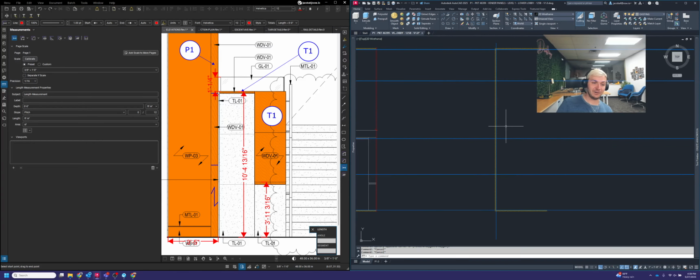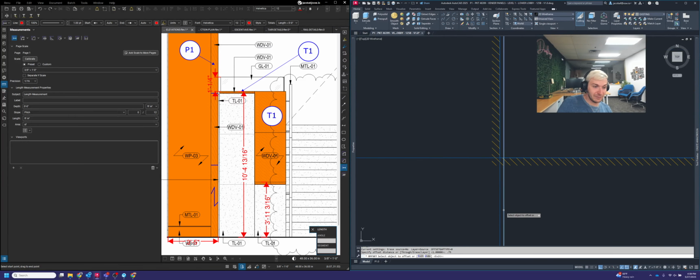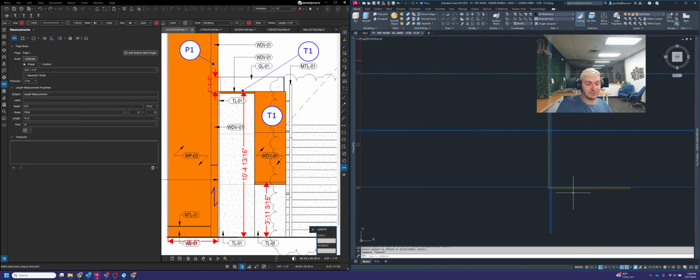Because we are using panel cleats here, we're going to use the offset command, and we're going to offset that line 1 inch out here, and then offset that line 0.75 from there. That 0.75 is representing the panel thickness, because unless a panel is constructed out of some kind of specific material, it's going to be made out of 3/4 inch thick material for us here. So with that being said, we have our horizontal indicators and our vertical indicators showing where the panels are going to sit.